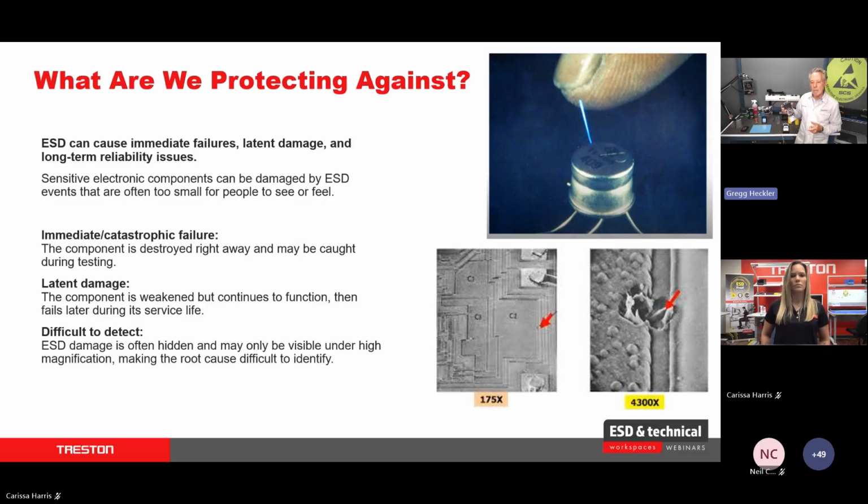And then the other problem is that when we charge conductors up and then ground them, like pulling an IC off a reel on a pick and place machine, it comes over, has a charge on it, sets down on the trace or the pad of that device, zap. That's what we call CDM events. Those are events where we have conductors charged by these insulators on my workstation. Those usually create a partial damage or a latent defect. That's where the costs come in. You don't detect that in your test department. It goes to your customer and later on fails. That's 10 times or more costly than the HBM event.